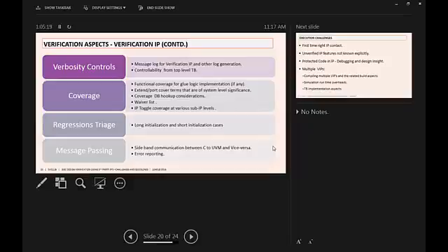At your IP level, you have design IP, and your UVM components are driving from the outside. Once you introduce the IP into the SoC, your C will drive, I mean, the processor will drive. How are you going to reuse that input-side UVM here?